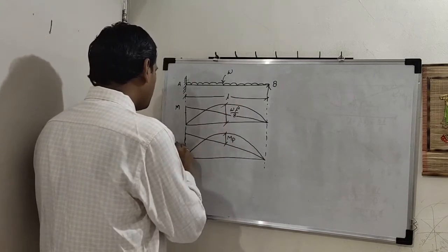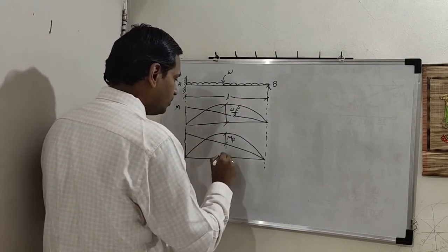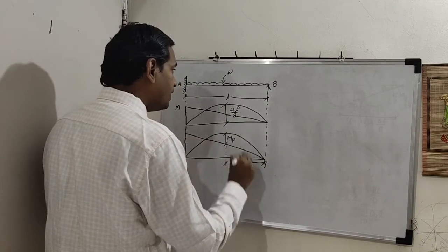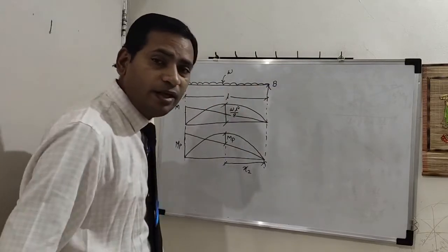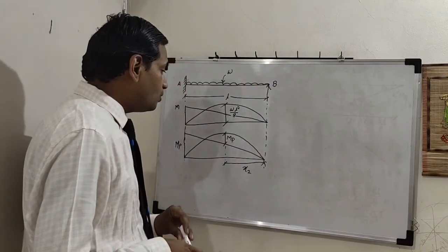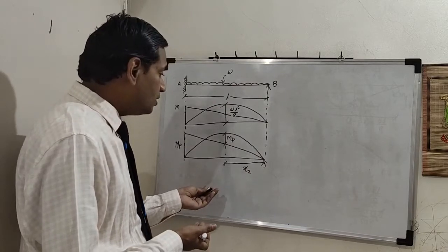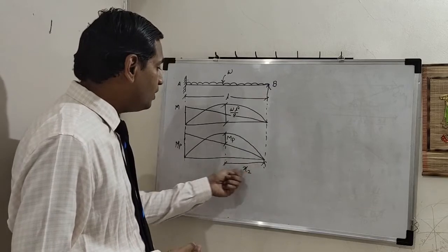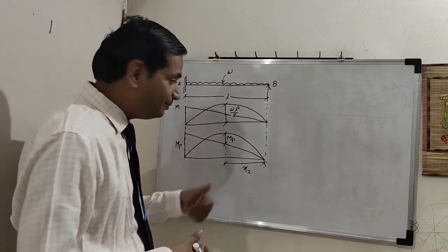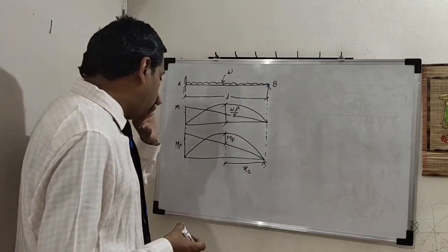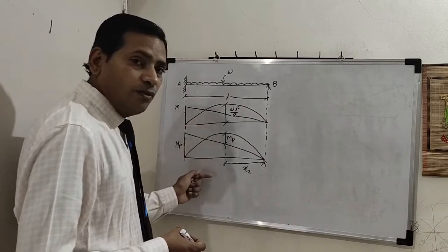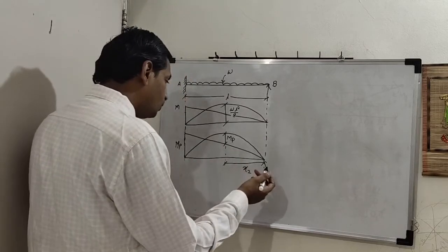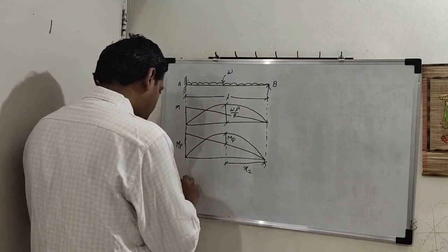Okay. So we shall assume that we have a plastic moment corresponding to collapse load, which is occurring at x2, because from the given loading diagram we cannot identify the location of plastic hinge. So for simplicity we have assumed x2 as the location from end B where plastic hinge will be formed. Now we have a section at x2, so what will be moment Mx?